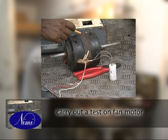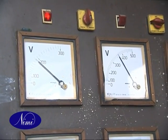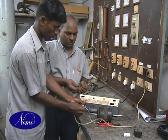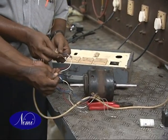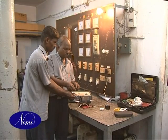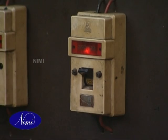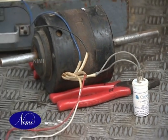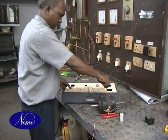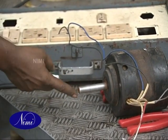Carry out a test on fan motor. Prepare test cord with a 200 watt bulb in series. Plug the test cord to the test board and switch on. Touch both leads. If the bulb glows, the circuit of the test cord is complete. Disconnect electric supply. Keep the unit on the workbench. Plug the unit in the test board and switch on. On the fan switch, if it runs, the fan motor is in good condition.